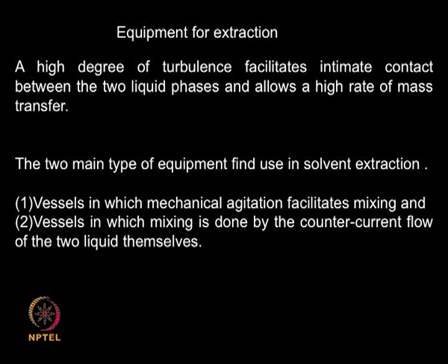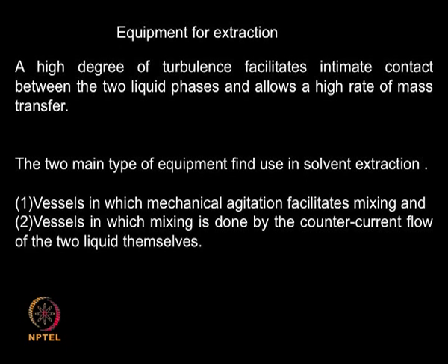So in all the labs we always have a separating funnel which is tapering downwards, but in large scale operation you may have to resort to many different types of mixing separating systems because of many problems which we said, because of non-ideality, because of the viscosity conditions, and you want to do this entire operation very fast. So the mass transfer limitations, the movement of the solute from the heavy to light needs to be speeded up. So you need to create turbulence between the two different liquids, so that the solute moves very fast from the heavies into the lights. So it is not only the thermodynamics, you are also wanting to improve or speed up the kinetics.